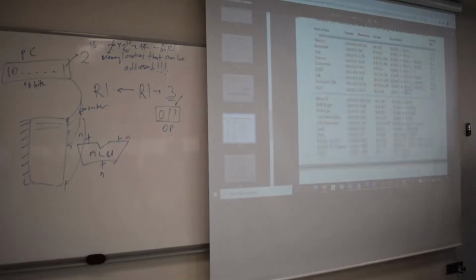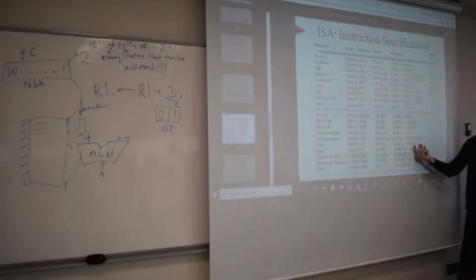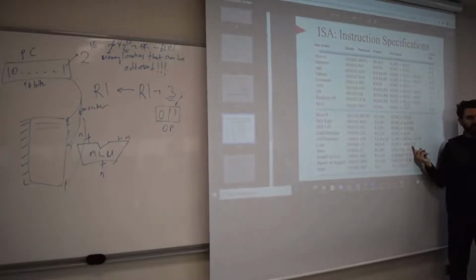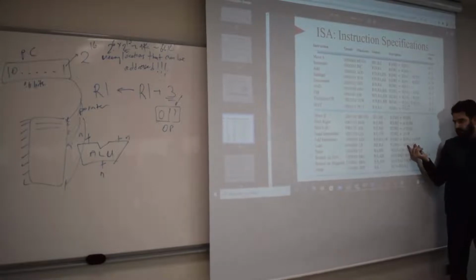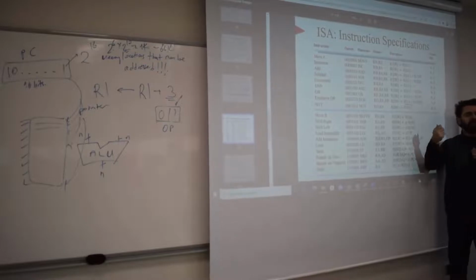Okay, here we have load. You see load? The register content is an address. So you go to that address, just provide that address in source B. Remember the bus B? That is bus B. That is sent to the memory. And memory read is enabled.